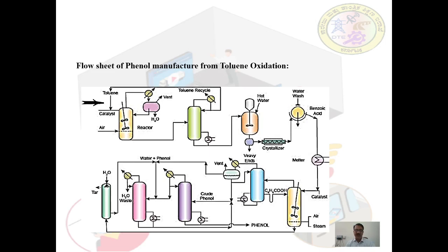Top product is obtained after partial condensation followed by phase separation. The phase separator produces three streams, namely the vent stream that consists of nitrogen, carbon monoxide and carbon dioxide, the aqueous water phenol stream and organic crude phenol streams. The crude phenol stream is partially sent as a reflux to the fractionator and withdrawn as the product as well.